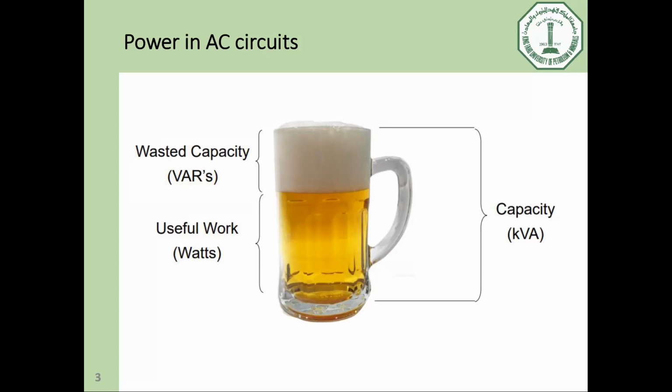P2 is just some ripples for power. However, the average value of these ripples will be 0, because the average value of the overall power will be the part of P1, which is a function of cosine theta. Right. So this was a very important part, and you have to recognize it because this is one of the basics of electrical engineering.